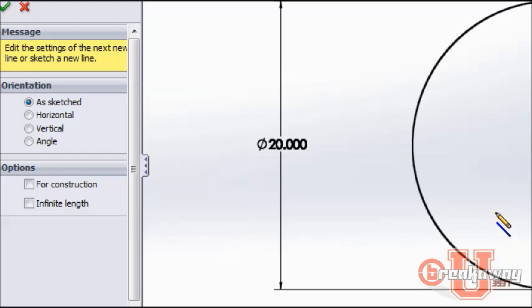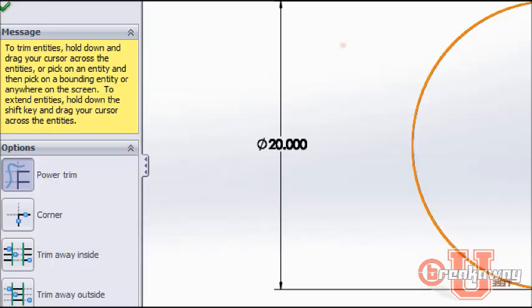Something that's really nice is SolidWorks has now created this into two hemispheres. It no longer treats it as a larger circle in terms of what I'm about to do, trim entities. Now you'd think if I trimmed through this circle, that it would delete the whole thing. Well, SolidWorks is now treating it as, in essence, two separate parts put together. Boom. Now I've just erased only half. Now the radius still holds true, and this line is still centered. All your relations are going to stay true on that middle as well. And that could be cool. Now notice I've created my hemisphere. Pretty neat stuff.